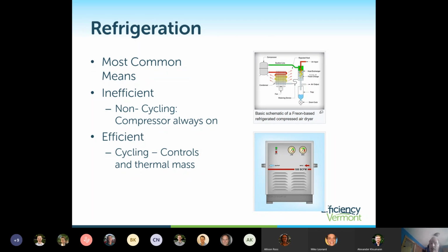The one efficiency penalty that you have on most refrigeration dryers is that it's a dumb system. It's designed to drop out moisture at a 90-degree day with high relative humidity all year round. Well, we don't have 90-degree days with high relative humidity all year round, but with these systems, the compressor operates as if it is always trying to remove moisture and a lot of it.